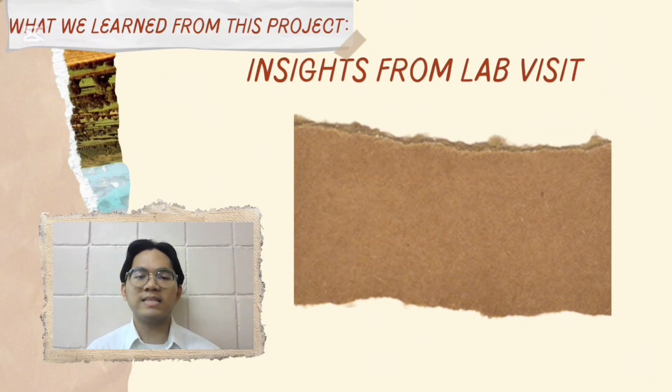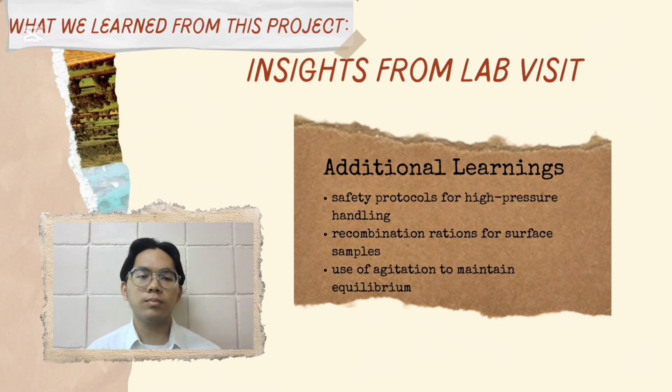We also gained insights into, first, the safety protocols for handling high pressure fluids. Second, the use of recombination ratios for surface samples. Third, how agitated lab cells maintain equilibrium during tests.